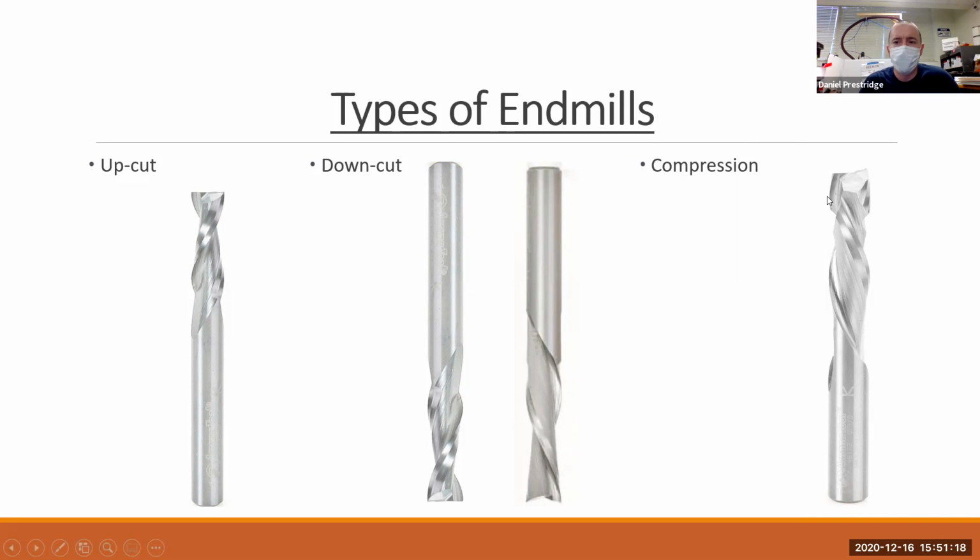So you typically don't run that, but if you do, you go essentially full depth of cut all the way down into the material and just move through it at some rate and it'll cut through everything. I've done 80 to 100 inches per minute, full depth of cut at like half inch depth of cut, full material, and at I think 17,000 or 18,000 RPM.